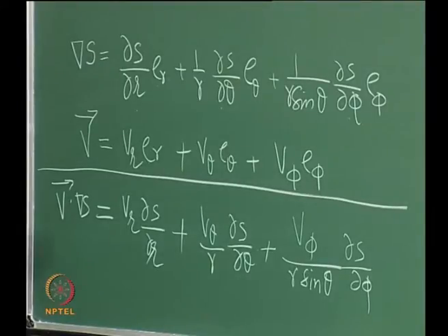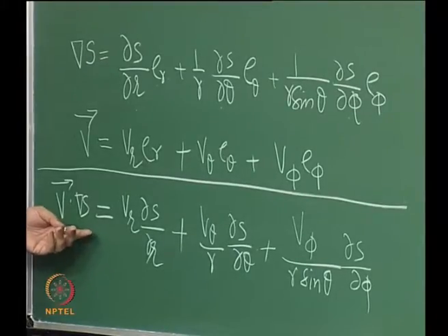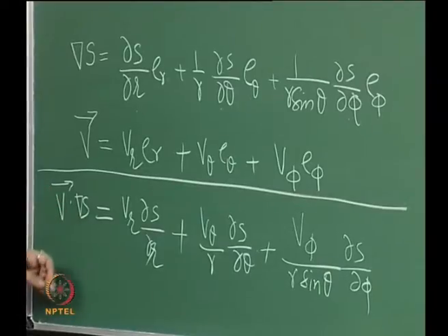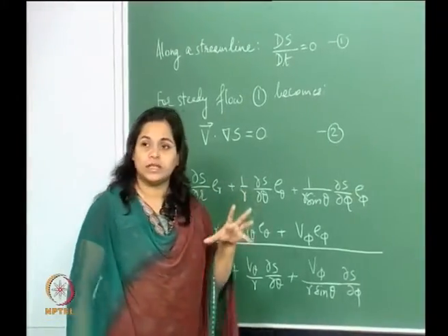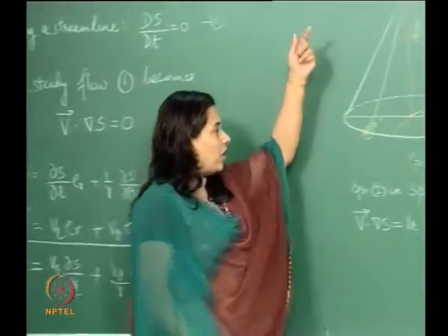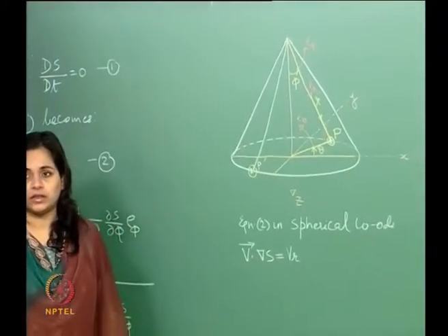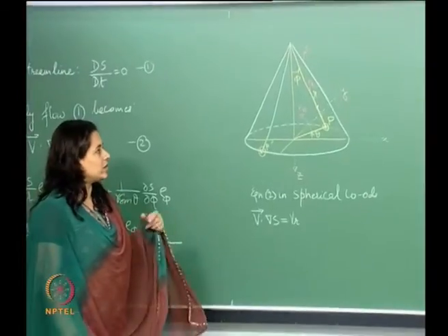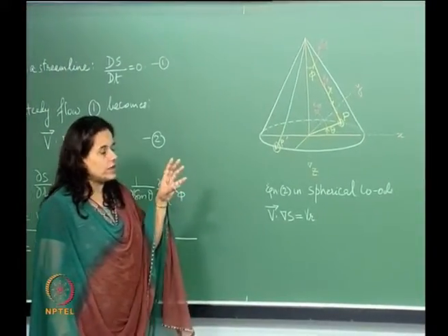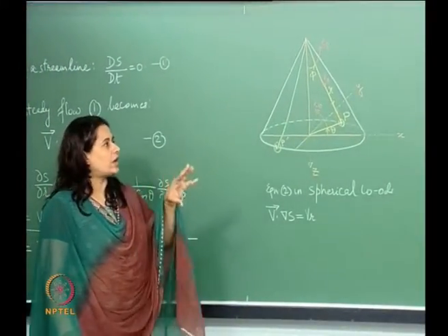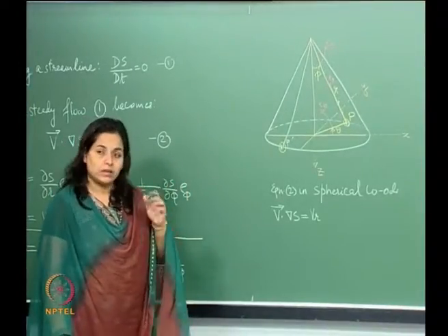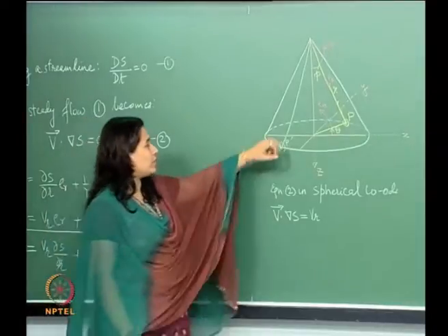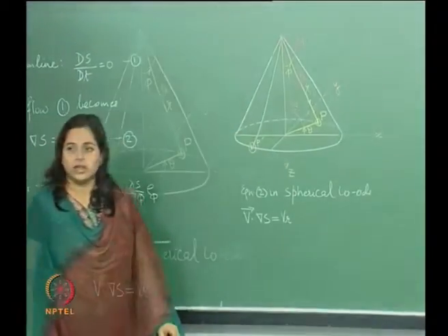Now, from here what we know is that the conical nature of the flow is still maintained, and the property along a radial direction is constant. We had talked about this earlier. So, in the cone at 0 degree angle of attack, and for the cone at a certain angle of attack as well, the property along the radial direction is still constant.